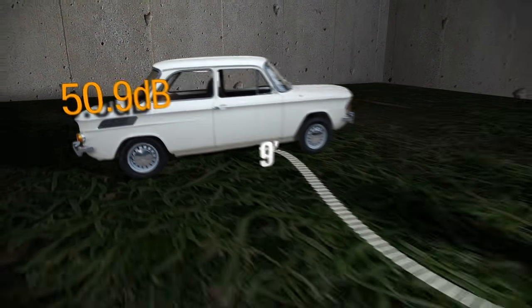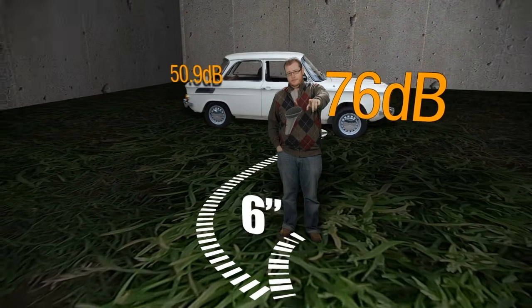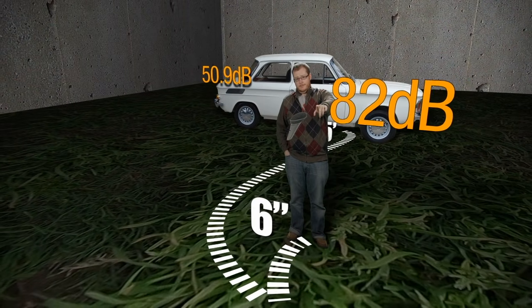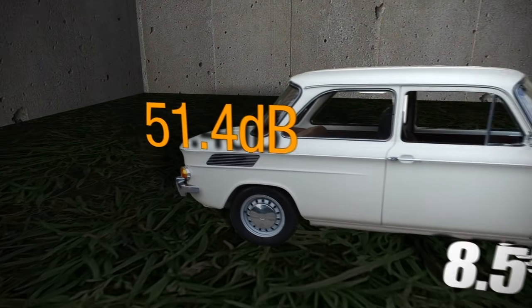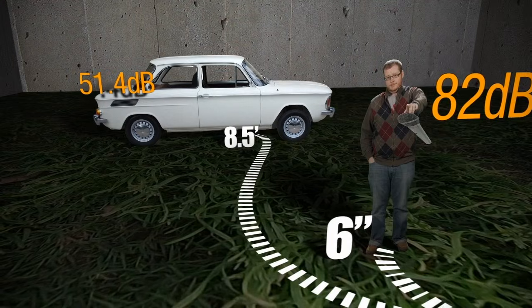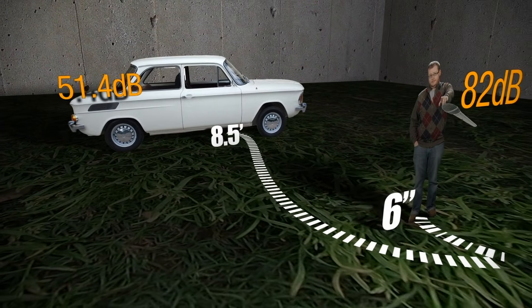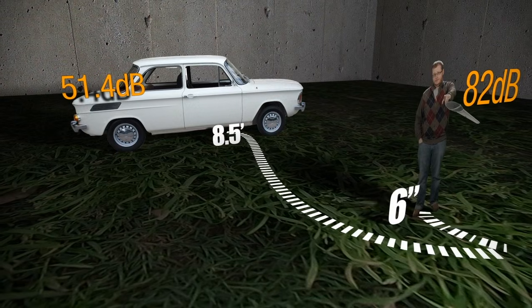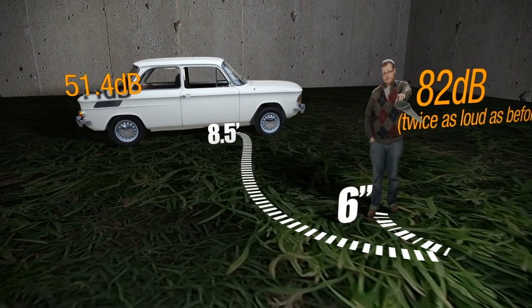If you cut the distance in half again and put the microphone 6 inches from your subject, they would increase again by 6 decibels, but the car would only have increased another 0.5 decibels. Making this change would have resulted in your subject being 12 decibels louder and the car being 1.4 decibels louder, which works out to making your subject about twice as loud without really increasing the level of the car.